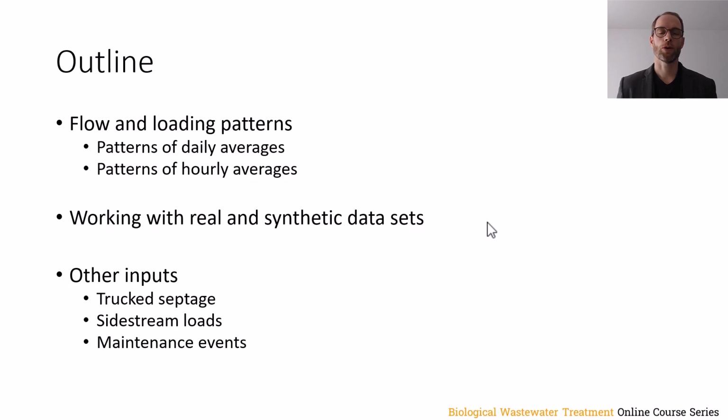That is to say, where we're varying the influent flows and concentrations of COD, TKN, total phosphorus on a day-to-day basis. And then we will compare and contrast that with simulations where the patterns are defined based on hourly averages. That is to say, where we're varying flows and concentrations from hour to hour. So we'll look at two different time resolutions and how that impacts our simulation results.